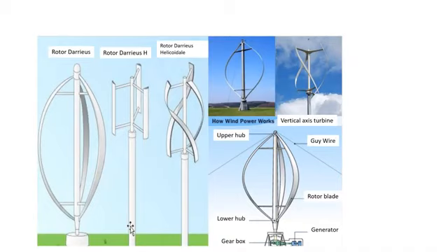The vertical axis wind turbines, or VAWTs, have the main rotor shaft arranged vertically. One advantage of this arrangement is that the turbine does not need to be pointed into the wind to be effective, which is an advantage on the site where the wind direction is highly variable. It is also an advantage when the turbine is integrated into a building because it is inherently less steerable. Also, the generator and the gearbox can be placed near the ground, using a direct drive from the rotor assembly to the ground-based gearbox, improving accessibility for maintenance.